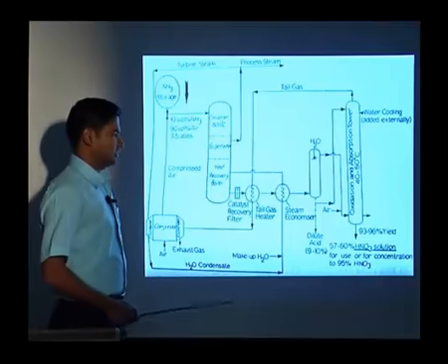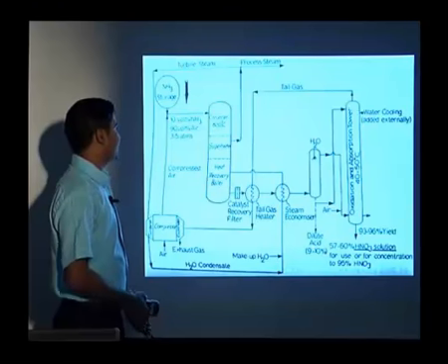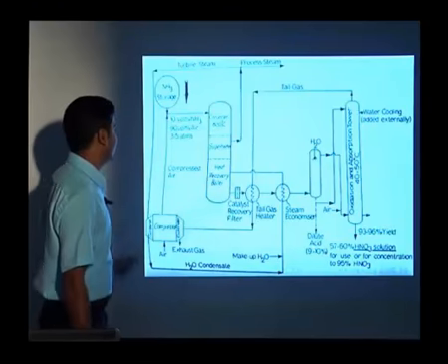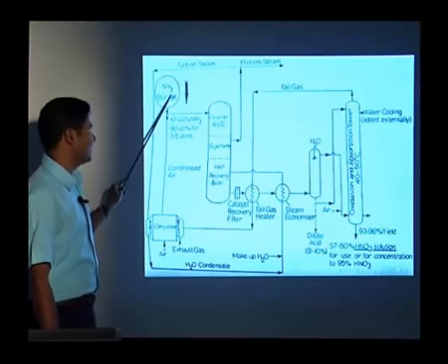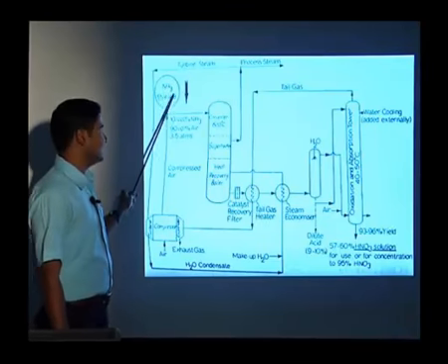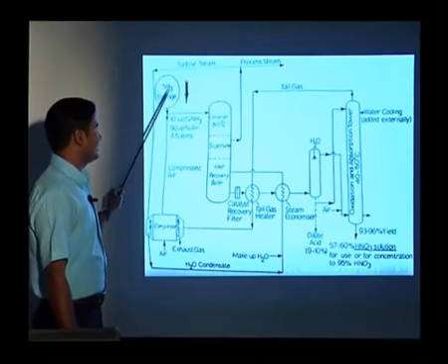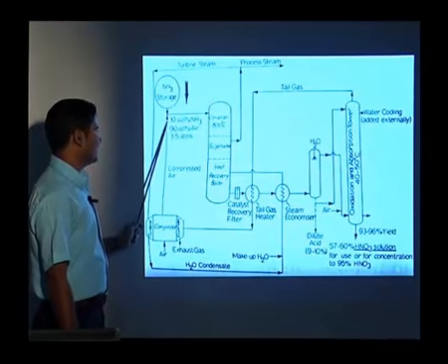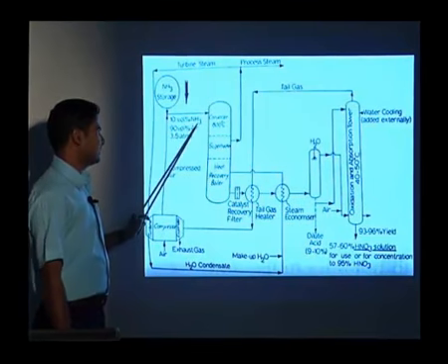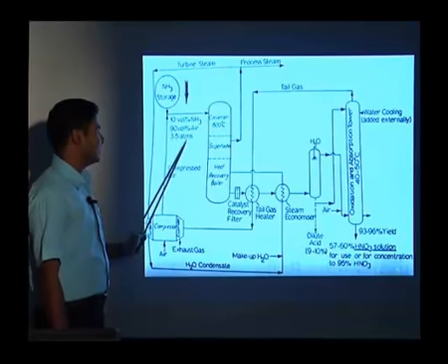So if we see the production of nitric acid PFD, then we can have the raw materials as NH3 and the air. So here you can see the NH3 from the storage. Ammonia, we have already produced by the synthesis gas. So that will come over here to form the nitric acid. The ammonia from the storage and the compressed air are mixed: 10 volume percent of ammonia, 90 volume percent of air, and the pressure we kept at 3.5 atmospheres.